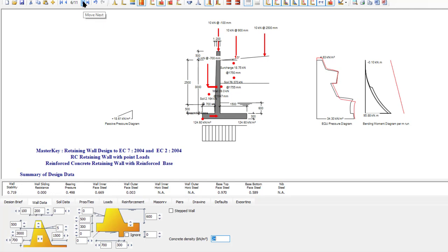Now we're getting the complex loading. We can have loads on the soil, such as a house, a strip foundation on a house of 10 kilonewtons at 2.5 meters out, but probably slightly more than 10 kilonewtons if you're dealing with a 600 wide strip. You'd probably argue it's about 60 or 100 kilonewtons. And then you have another one here at 900, so possibly it's 2 axles of a vehicle.